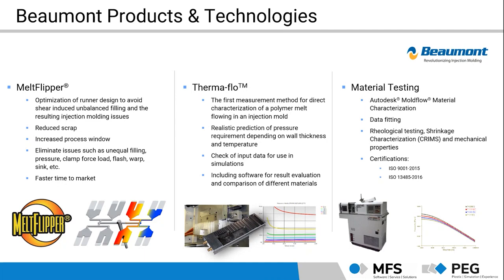So this is a measurement which was developed by Beaumont and which takes these typical things like frozen layers, which play a big role in injection molding processes, into account. So this is, let's say, the first measurement method for direct characterization in an injection mold. And the third point here is the official Moldflow material characterization service, which offers material testing and creation of the UDB files for the use in the Moldflow software.